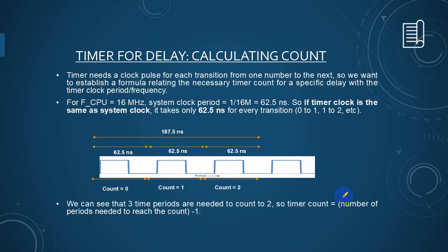But the technique is like this. If you divide the main clock frequency by the prescaler, you increase the cycle time. As you increase the cycle time, you can imagine this: with an 8-bit counter, within 256 counts multiplied by the larger cycle time, the timer span will increase. That's the main technique. We want to count different ranges of timing by using different prescaler values. So let's go with it.